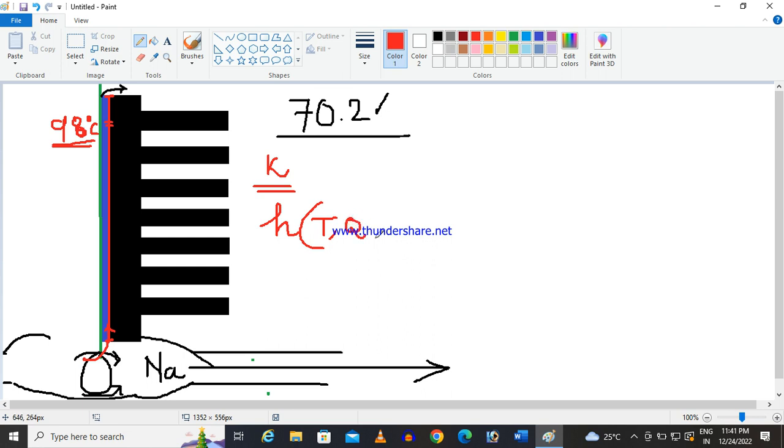So if the temperature is high, your heat evacuation is also high through convection. It is the normal virtue of heat transfer. And if there is a flow, when we are blowing on hot food, the heat transfer is augmented. That's why the convective heat transfer coefficient, broadly, is a function of temperature and flow.